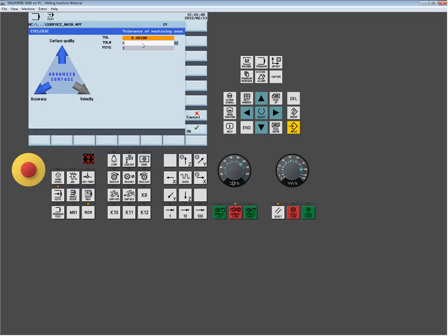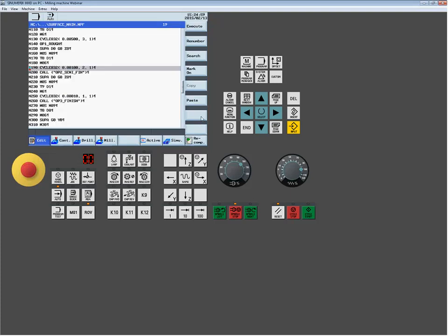So now if I looked at it, I was tightening up my tolerance, and I was down here in my semi-finishing. My two lower diamonds were triggered. And then from there, I went down to the full finish. This is where I was really concerned about my dimensioning accuracy and the quality of my part.